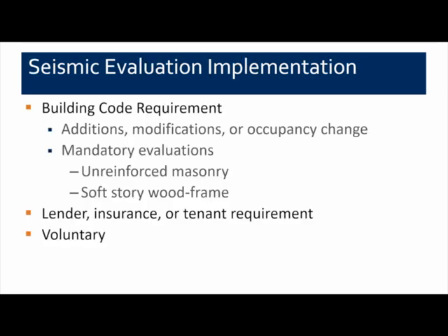So when you want to do an evaluation of an existing building, there are important considerations as to when you would want to do this. One common type of evaluation is triggered by the building code, and this is normally going to occur if you have additions, modifications, or a change in occupancy of the building that would trigger a seismic evaluation of the building.